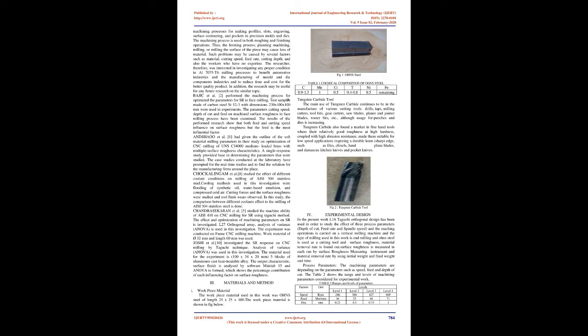In this paper they conducted experimental work on a vertical milling machine using a tungsten carbide tool cutter, and copper material was machined by the milling process. They considered speed, feed, and depth of cut as input parameters for finding material removal rate and surface roughness using RSM and GA. They analyzed the effect of process parameters on MRR and surface roughness, 2012.